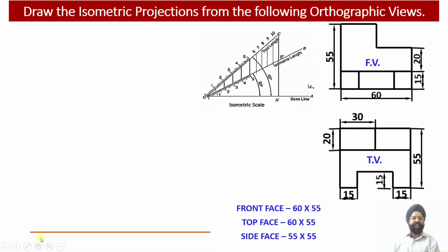Now let us move on to the construction of the isometric projections of the solid. So first thing we need to do is, we have drawn a ground line which is the datum line. So a horizontal ground line or the datum line has been constructed, and we have marked an origin point onto this horizontal datum line, and from this origin we are going to draw the isometric x-axis towards left at an angle of 30 degree.